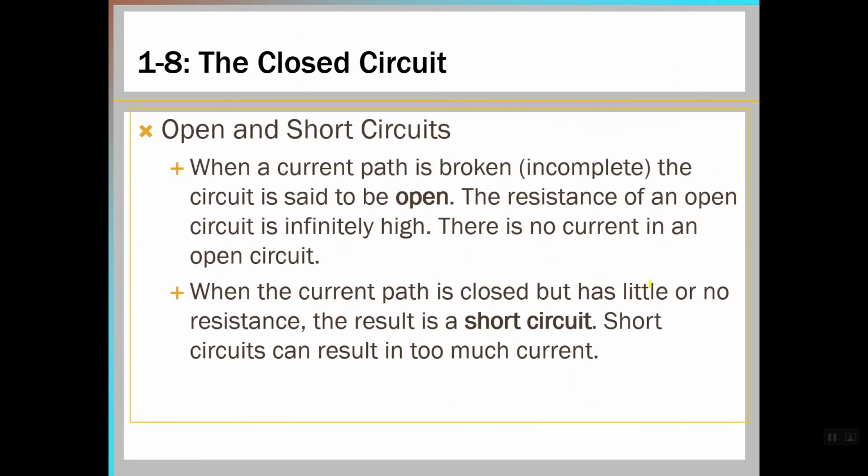An open circuit is when something's broken, you have an incomplete circuit. If you put a meter on it, you measure it, it has an infinitely high resistance. It'll just tell you it's an open circuit. If you have a closed circuit, or a short circuit, that means something is being bypassed, allowing the current to flow in a path that you haven't defined or that's not part of the circuit. And it could be your body, so you have to be careful about that. You may not feel it, but it could still be going through your body.